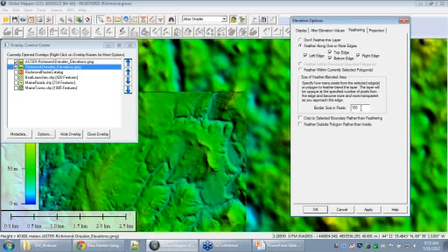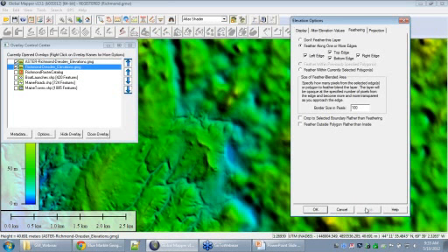And you'll see there's a border size, how big the feathering region is going to be. In this case, we're going to feather over 100 pixels in that elevation grid. All we have to do is click Apply down at the bottom, and that's going to blend those two surfaces into each other. It's going to smooth out some of the lumps and jagged edges as we hit the edge of one of those grids and blend it into the other. That's going to smooth it out for things like analysis when we go do watersheds and viewsheds, lines of sight, cuts and fills, all those sorts of things. So that's how we combine 2 of those different data sets.